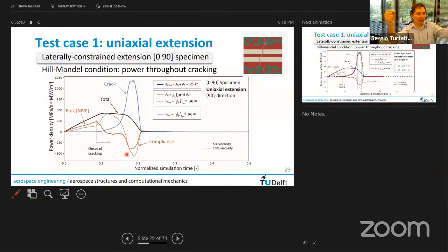I mean, as you pull and you're deforming the bulk material elastically, and the inelastic process is actually occurring at the crack itself. And so we dissect, in a sense, what is the purely fracture process from the elastic deformation in the surrounding material. So the line here in blue is what we should match for the crack.